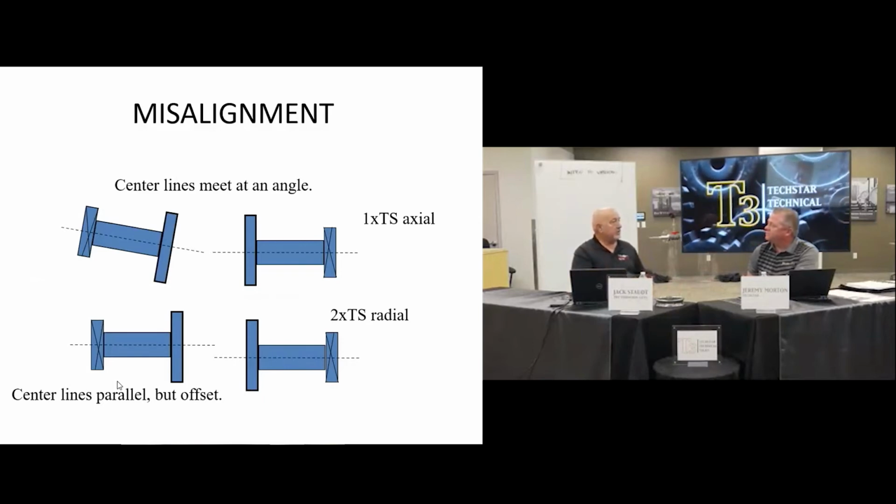Just similar on one here recently, the machine was put back in service and aligned in, I think it was February, in a really cold area of the world. When they did the alignment, the temperature was like 19 degrees. So they did a cold alignment, and in the summertime the temperature gets up to 105.